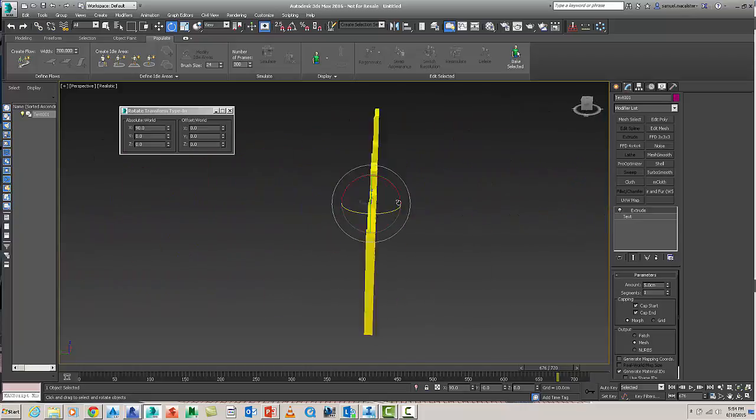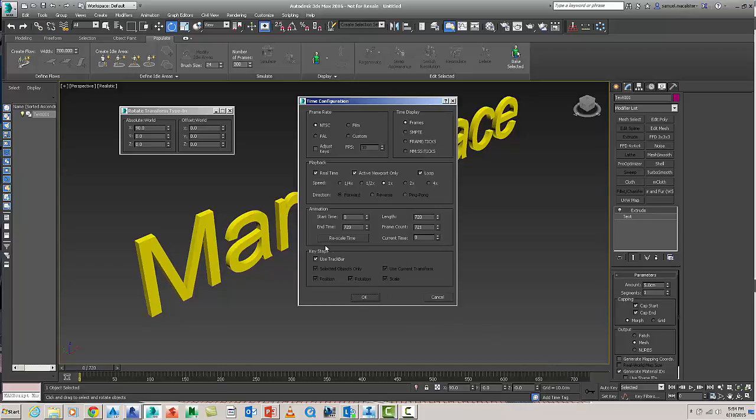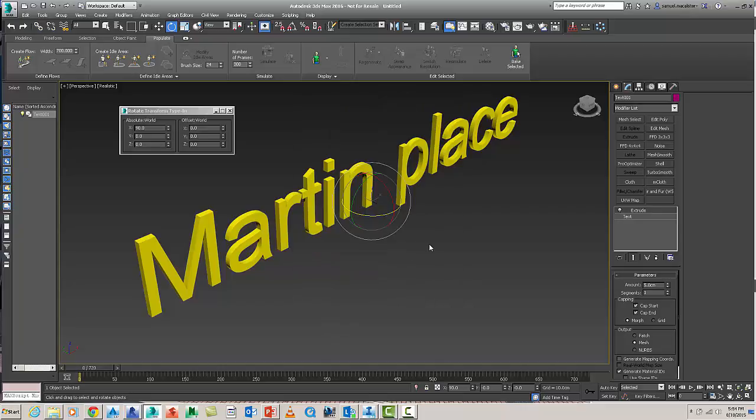And then finally, to get this spinning, I want to use our animation timeline tool here to create that. So what I've got is my timeline set to 720 frames. You can configure this here under the rescale time tool in time configuration. Leave the rest on defaults.